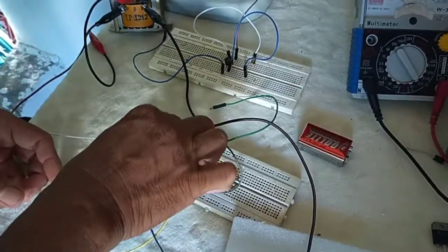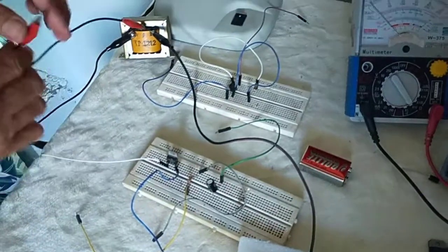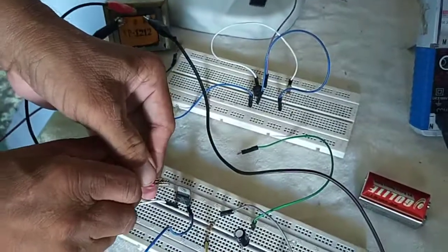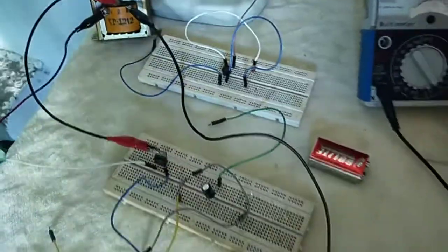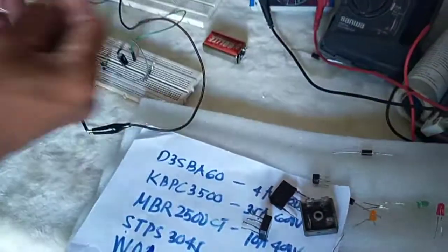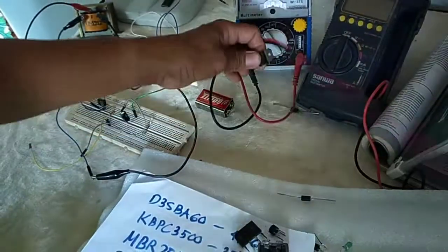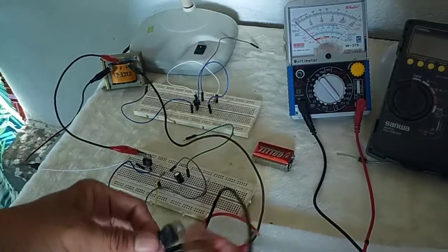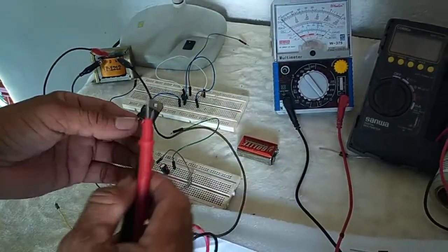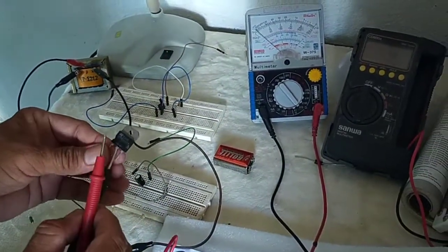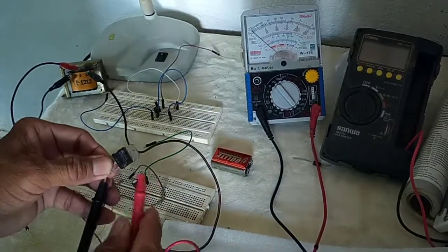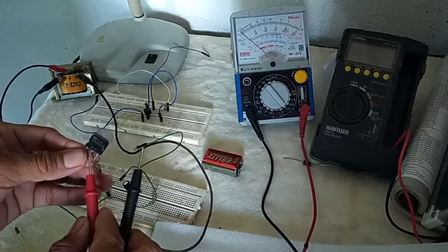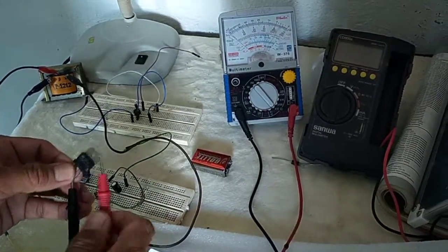Okay, here. The third terminal or the center terminal is connected to this metal case. For the metal case, actually, the metal case is the center tap. See, let us prove. If there is continuity, center terminal to this metal case, there is deflection, meaning to say they are connected together. They are connected, oh. See?